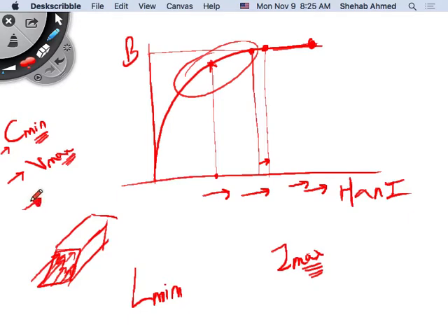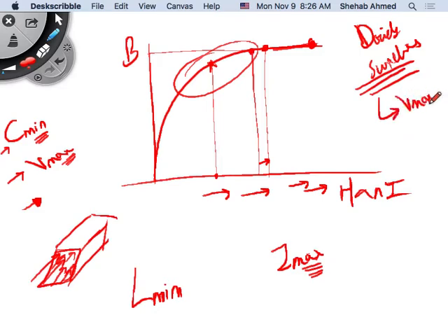We said it's something that's affecting the temperature, the lifetime. No, ESR is not, it's something that you will get based on the capacitor that you select. But how do you select the capacitor? Remember for the switches, what did we say? For the diodes and switches, what were the two most important parameters? Vmax, the voltage across the diodes or switch, right? And then, what was the other parameter? We went to the manufacturer's website and we chose based on two parameters initially, right? What was the other parameter?